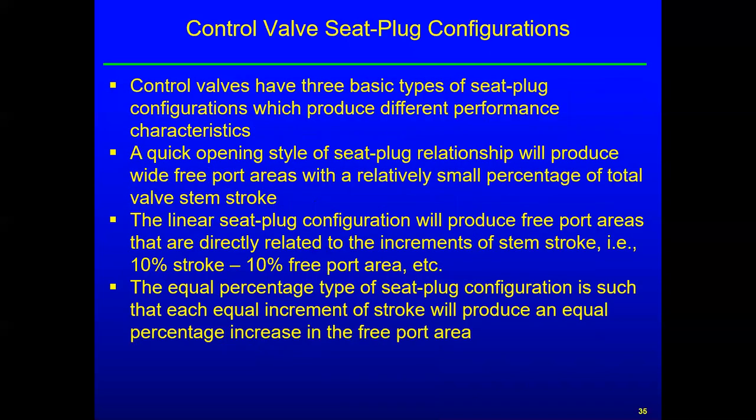Okay, so control valve seat plug configurations, there are 3 different basic types of seat plug configurations. There is a quick opening, there is a linear, and there is an equal percentage. And you can read those definitions. What you really need to understand is the curves on the next slide. So I'll let you just read those definitions on your own.